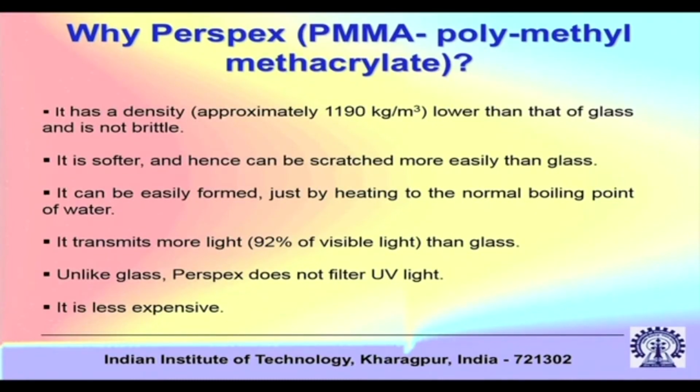So both up milling and down milling facilities are possible in micro channel. Typically when we are using micro milling, we are using a material which in loose name is called perspex, or some people call it plexiglass, and it is actually a polymer, PMMA, polymethyl methacrylate. Just like PDMS, it is also a very common material in making microfluidic channels.